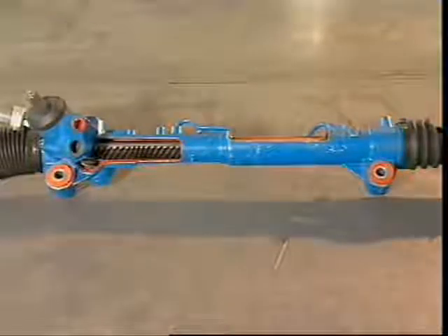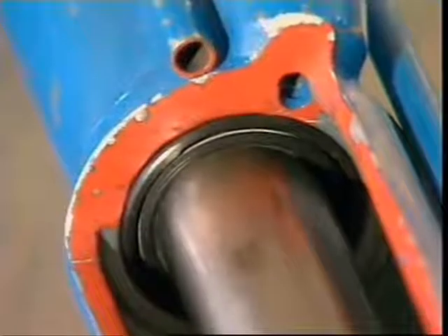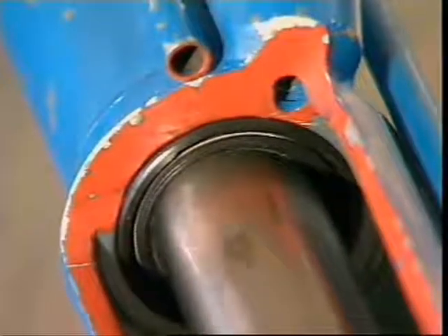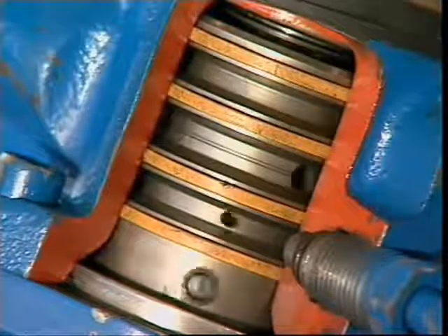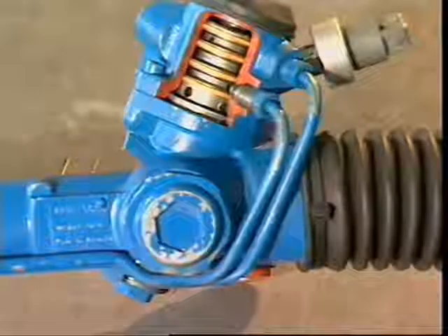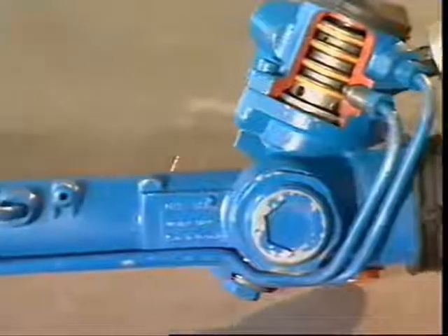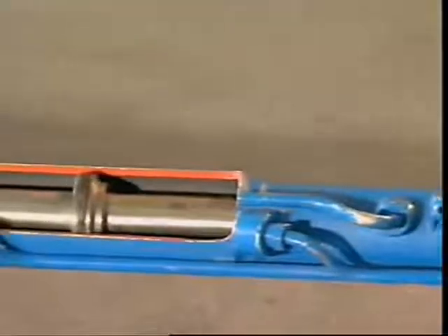In a rack and pinion steering gear, the piston is formed centrally on the steering rack, and the rack housing provides the working cylinder. Seals at each end of the cylinder isolate the power section from the rack and the helical pinion. Seals in the rotary valve section at the pinion input prevent fluid leakage there. Connecting pipes transfer fluid from the rotary valve housing to one side of the piston or the other to provide assistance which acts directly on the rack.